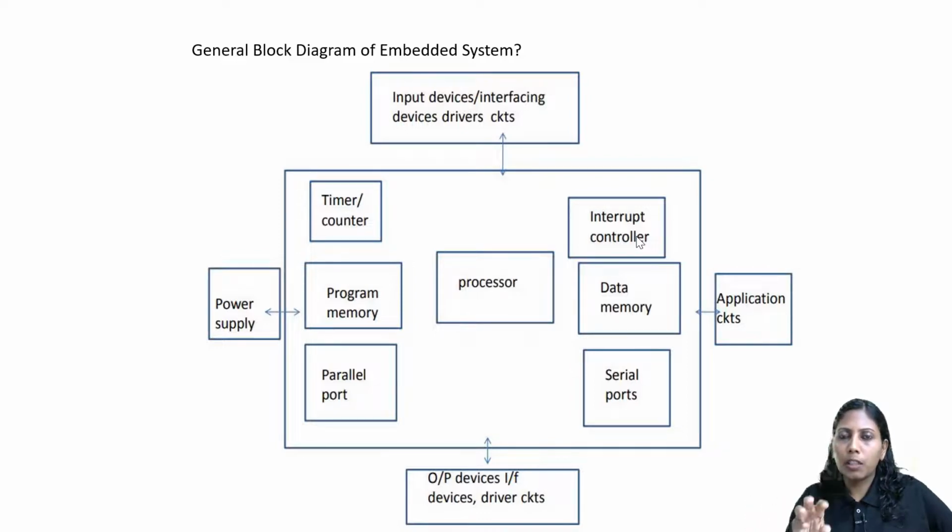For example, if I am washing clothes in cotton and select the cotton option, they have already set the water temperature and other things. For example, the water temperature is 40 degrees and the RPM is 800, or some basic data they would like to store beforehand, that means they decided it while manufacturing itself. If the clothes are wool, that set of data can be different. So this kind of data will be stored in the data memory.